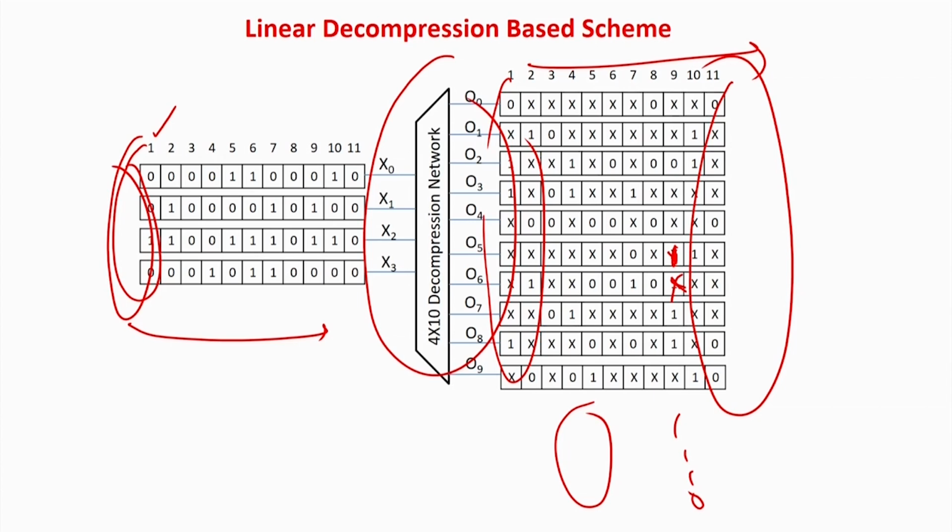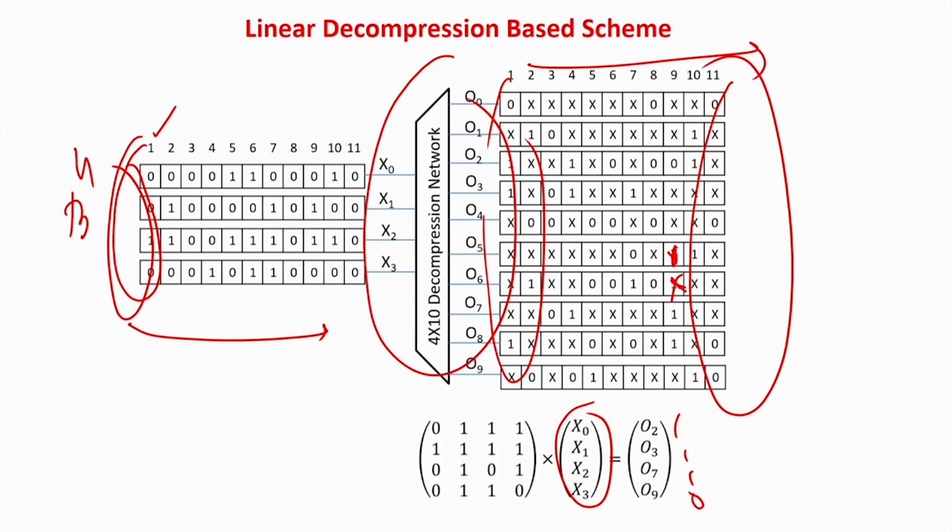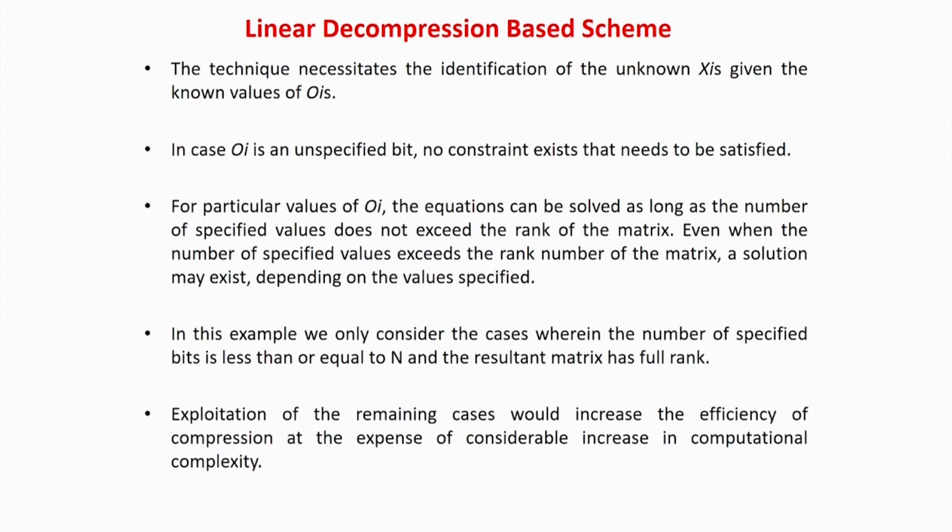So it happens in a queued fashion. It tries to find out, okay, I will only have 3 channels and this is the pattern required. I find out that there does not exist any linear circuit to do that. So either I can use 4, or I can somehow modify the test pattern so that it becomes compatible. So there are a lot of iterative heuristic algorithms to solve the problem. Now a slightly more theory I will tell you, about when it is possible.